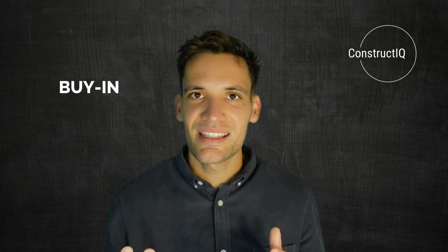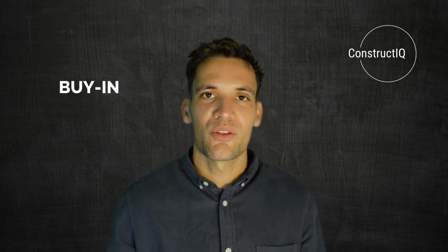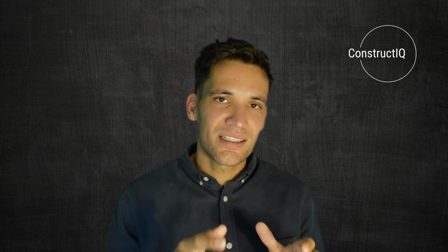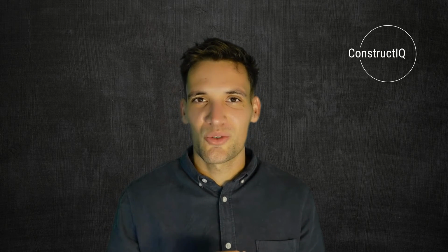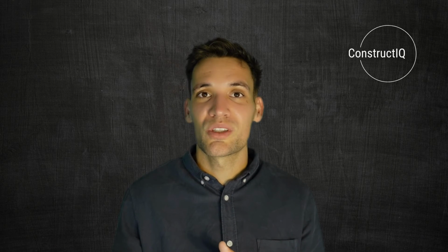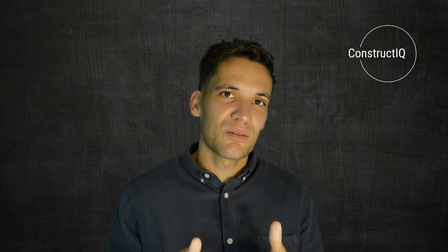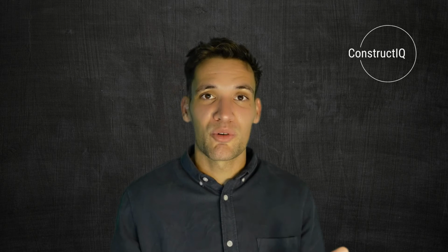Once we've improved and optimized the schedule, we need to get schedule buy-in. And this is another step everybody misses and people don't think about. There's no point creating a schedule if people aren't going to follow it. That's the point of scheduling. So we need to get agreement and buy-in from our stakeholders. So these are our internal stakeholders like the construction team, project management, the commercial team, our subcontractors. And then we also need to get buy-in from our external stakeholders. And basically the goal of this is ensuring the plan is realistic, everybody's happy with it, and we're actually going to follow it.